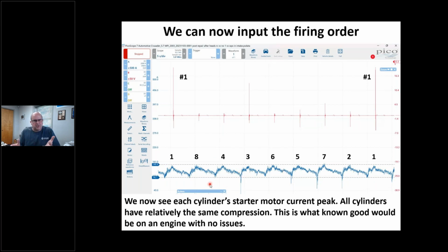Or if I got a modern diesel engine and I got a misfire code, or gas engine too, a misfire code to say P0302 cylinder 2 misfire. If I do this quickie test and I see cylinder 2 doesn't have much compression, is putting an injector in going to fix it? No. Is a can of Sea Foam going to do anything? No. Okay. So I have a mechanical issue. So there's probably nothing I'm going to bolt onto that engine that's going to fix it. I need to investigate the mechanical first. And again, this does not take a lot of time to do.